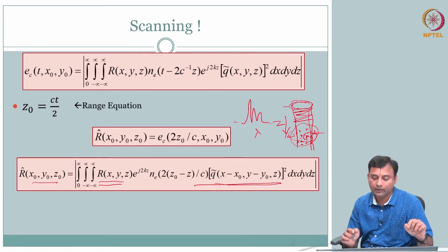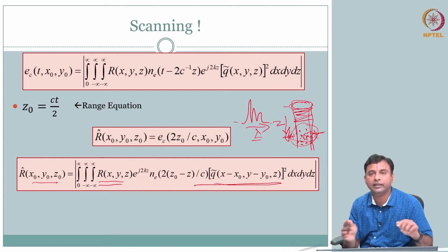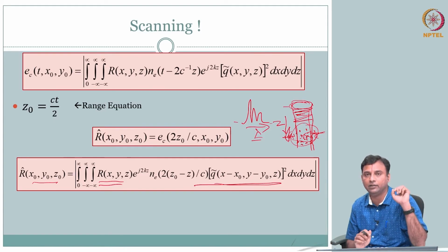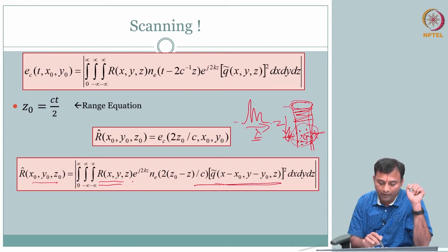However, you notice that is one important aspect. The resolution cell, which is in terms of lambda, has an effect on resolution. How much can you make it in the axial direction, and the beam width in the lateral and elevational directions. All of this dictates your resolution, and it is not the same. In ultrasound it is not the same. In the axial direction you have better resolution than your lateral width and elevational width. And then you notice one another term here.